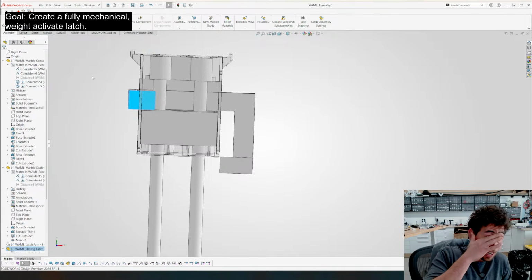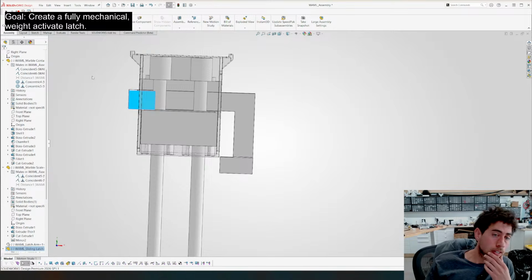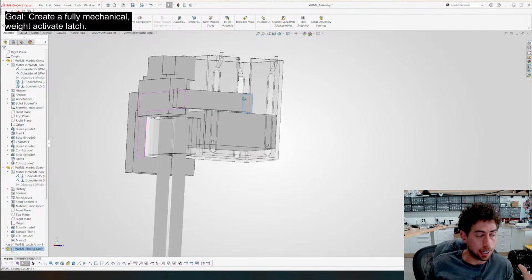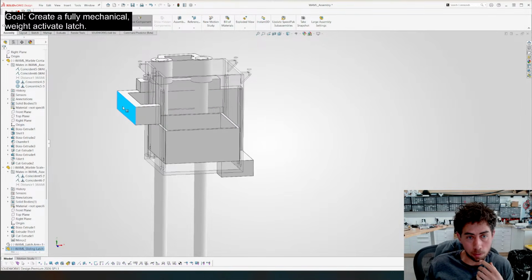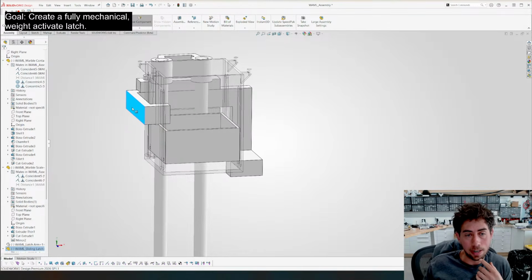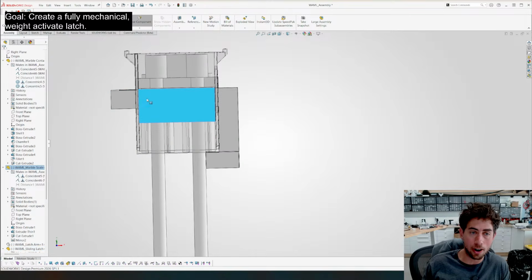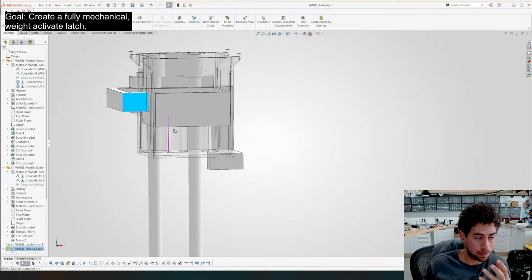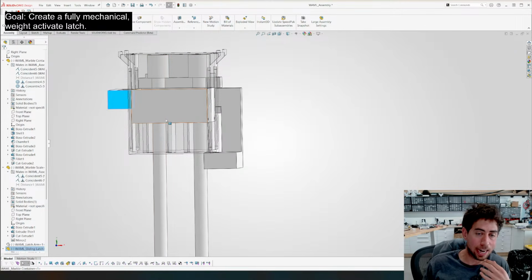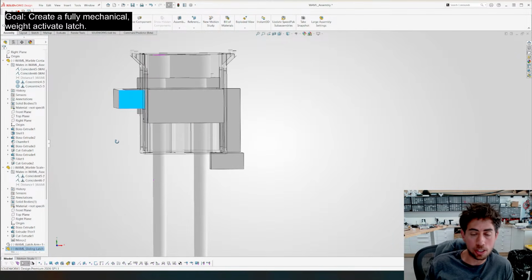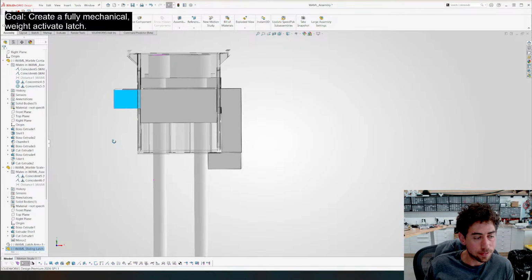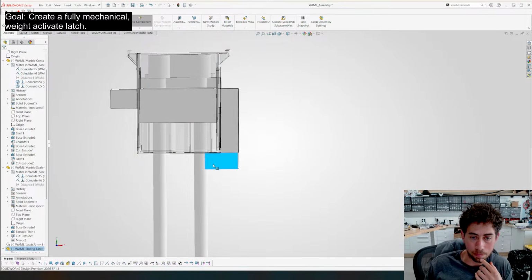Bearded printer says the spring just can't be so strong holding the latch against the box. Okay, so here's the thing. I think you're understanding exactly right. If this spring that's pushing this way is too strong, but the thing is we're working on different forces here. You would have to have a really strong spring to push so hard against this that this thing won't be able to drop, I think. Especially because we're adding weight to this, that it should be able to drop. Because we're working on two different axes on these, it's just the friction force of this that we have to overcome.